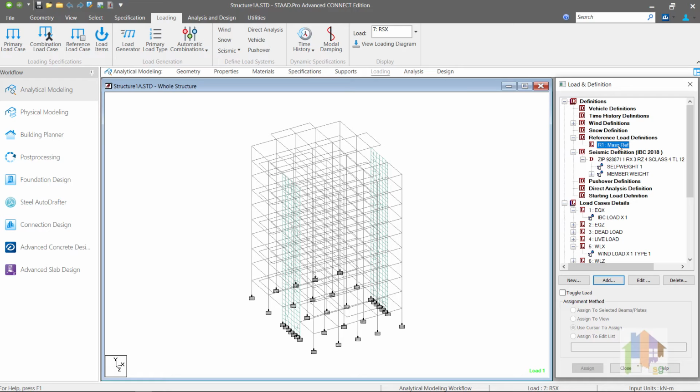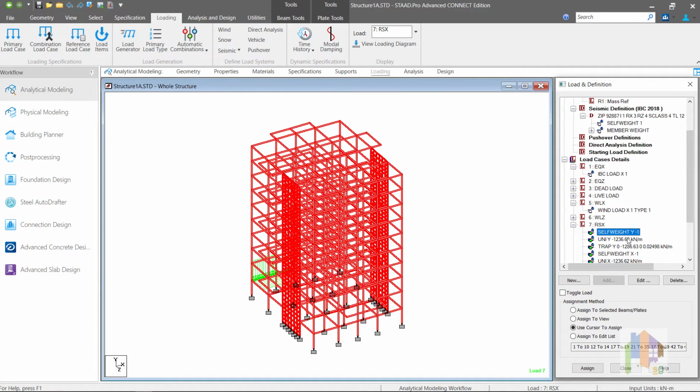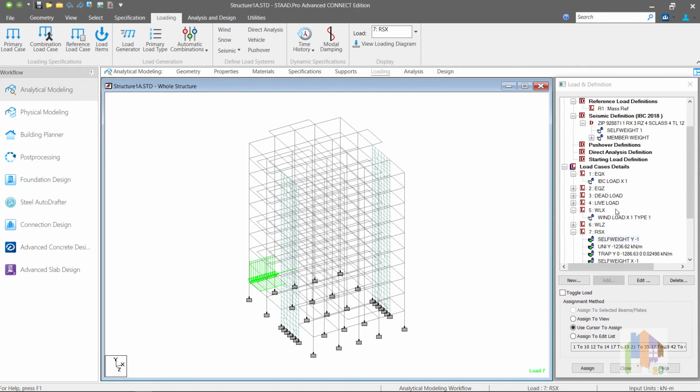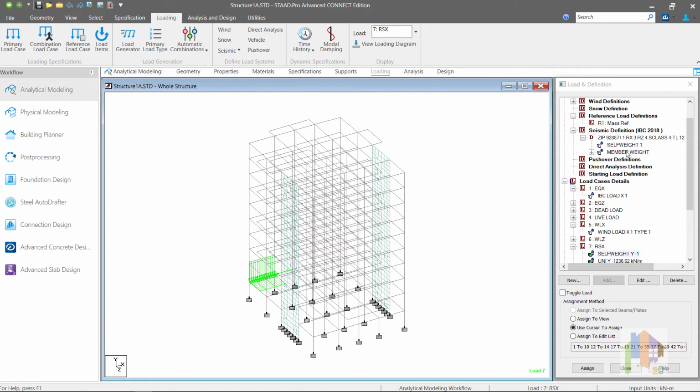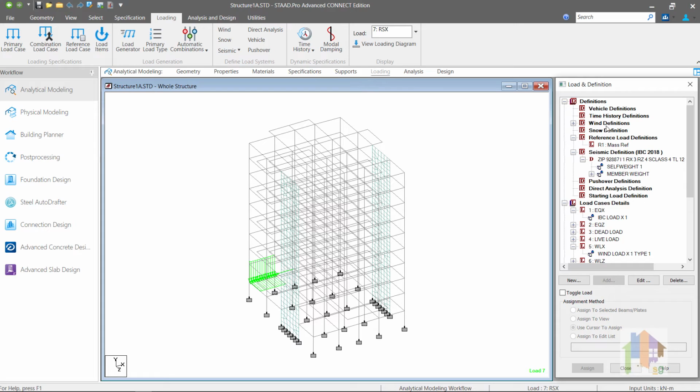For static seismic analysis, only gravity loads are used, and for dynamic load case, mass in 3 directions. You don't need to define seismic weight anywhere else. So you can simply define the seismic parameters for static seismic analysis and response spectral load for dynamic load. No seismic weight or mass model under the response spectral load case is required. The program will read the relevant seismic data directly from the mass reference load case and use it for static or dynamic analysis. No need to define the same load data thrice.